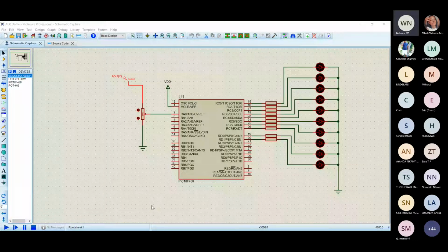That is a current transducer. And you use a 0 to 5 volts as a transducer to represent the pressure and so on. There are so many transducers. So if it's 0 here, it represents a certain value. If it is maximum, it represents a certain value, and you scale in between. For us then, guys,